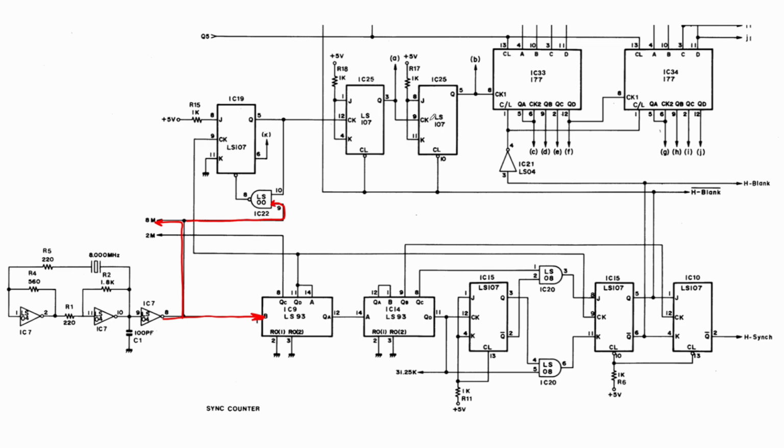And I had a quick look at the logic here. This is the stuff that eventually produces the horizontal blank. And I think the fact that this connection is broken explains why we see only 4 lines instead of 8 for the cursor character, and probably for every character.